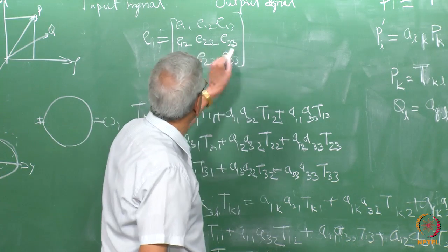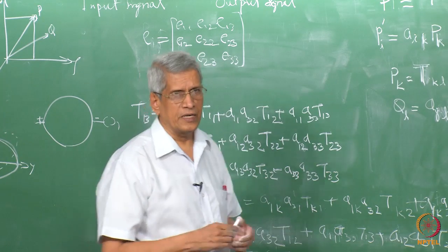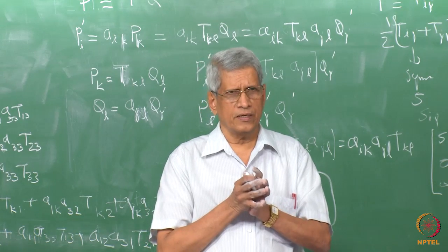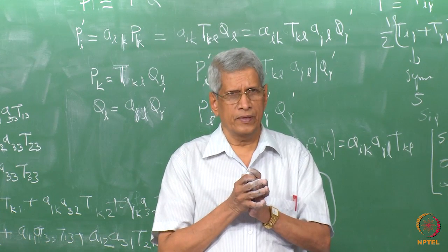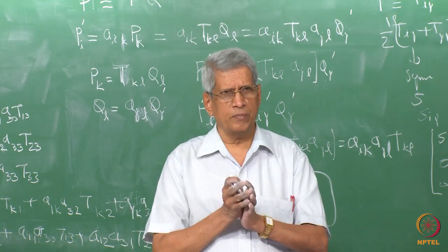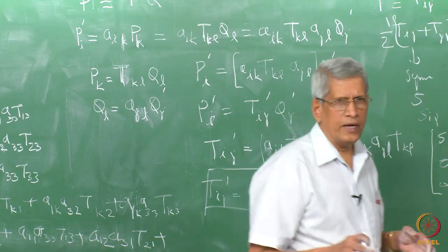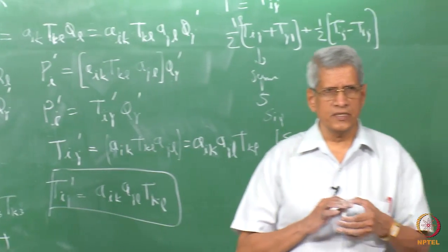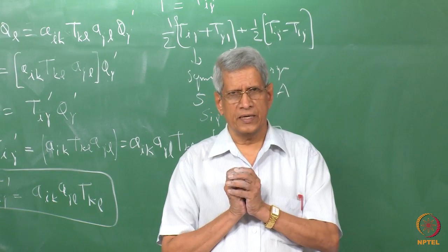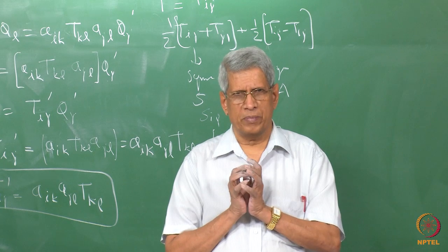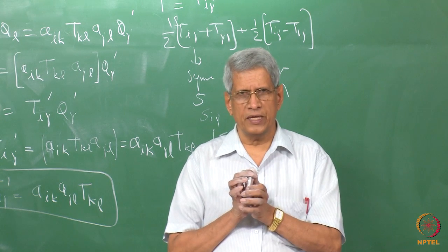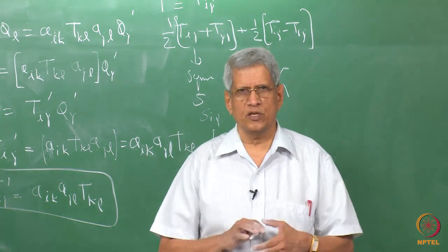These are all the shear components, this is the dilatation, correct? If we take a sample which contains all these components, that means if we take a cube and these stresses are applied, it changes into a parallelepiped. The shape change is going to be there, and there is going to be a volume change also.